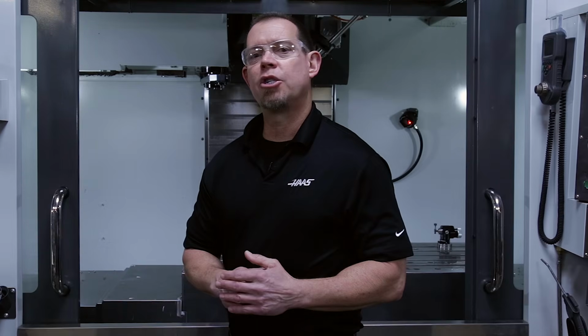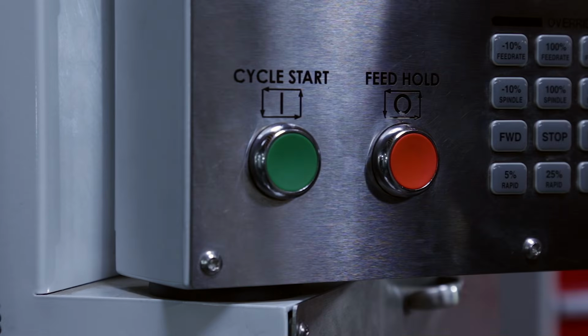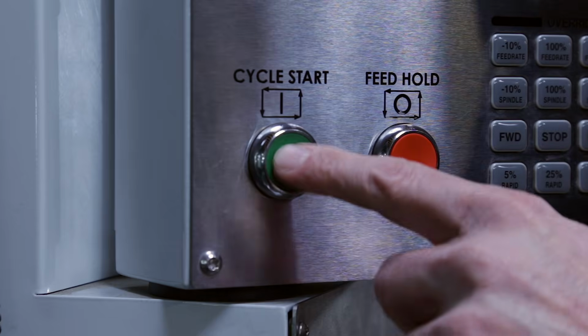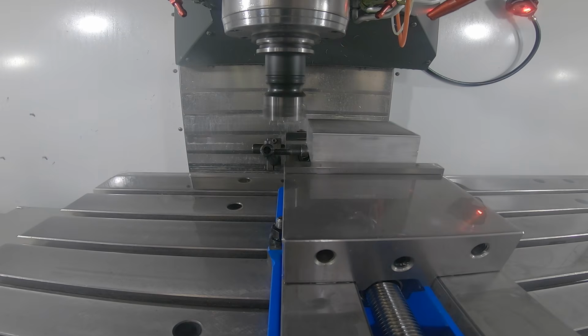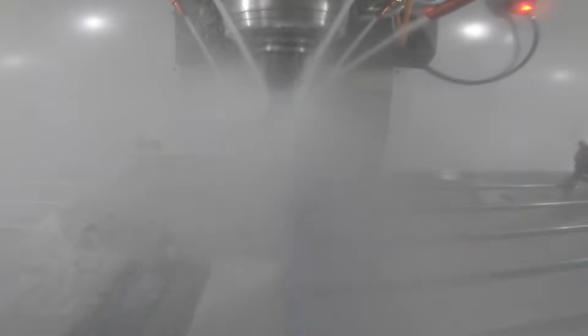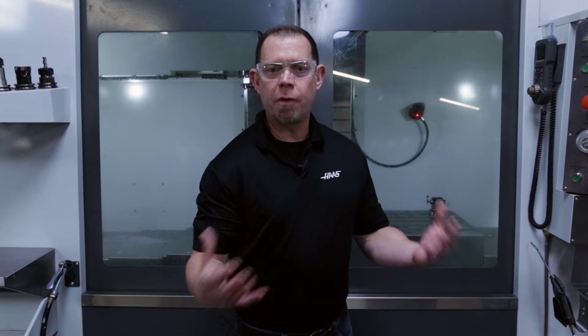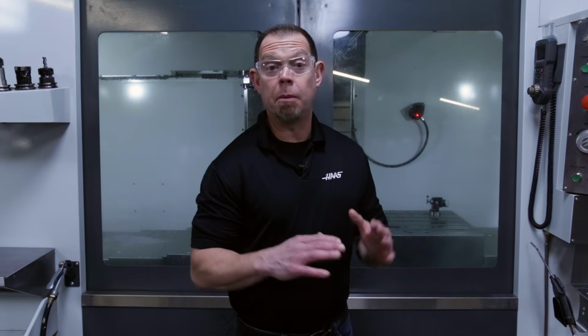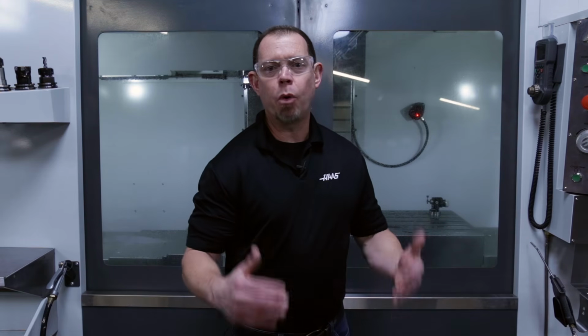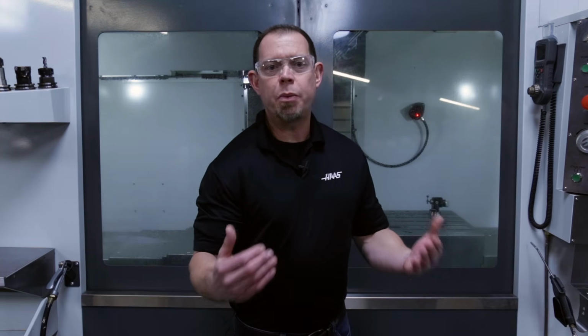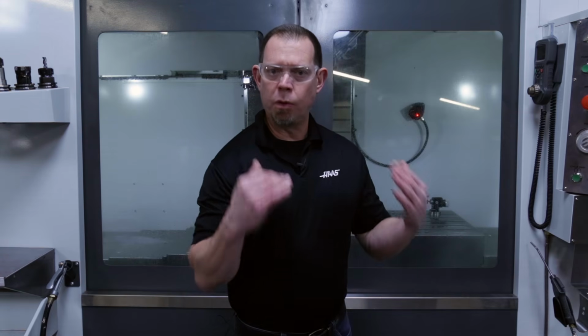Next, we'll talk about actually running a CNC program. CNC machines are fast, so once you hit the cycle start button, you really don't have time to react if there's a problem. Because this time is so short, machine operators need to be familiar with slowing down operation of the machine for the first part they're running out of a batch. This process consists of just a few simple steps, and we start our first part slowly so we have a chance to double check everything seems right before we start moving quickly. Once we know everything is working correctly, it's full speed ahead.